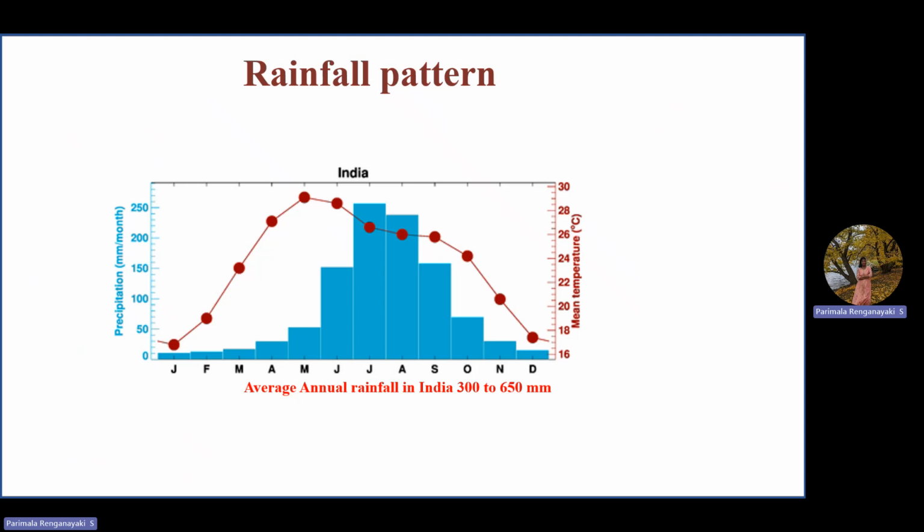During January, February, March, April, May, the rainfall is very less, whereas June, July, August, September, October, most of the rainfall falls during this period, and again in the other period there is no rainfall. So whenever it is raining, we need to manage the water. We need artificial recharge or managed aquifer recharge. So this rainfall pattern also clearly tells that India needs more water conservation methodology.